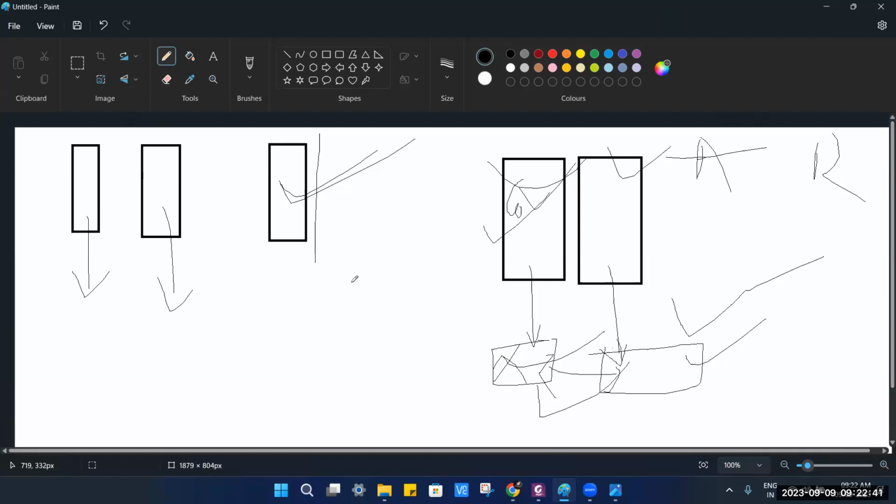So OBD packet format is there. So you are supposed to interpret that which comes in from the OBD reader. Right? Correct. Yeah. So is there any simple way I can do this? Because I don't have any direct reference except an Arduino code, which I'm trying to change by understanding. This I need to check, but mostly what I have seen, that OBD stack, if they are implementing in automotive, they are using AUTOSAR architecture. And in AUTOSAR, yes, you have a low level driver library which is separate from this OBD stack which you are saying.